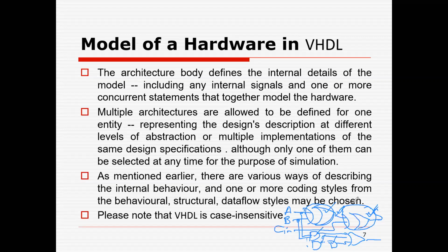I have already said that there are various ways of describing internal behavior, and one or more coding styles from the three styles which I mentioned. These are the three styles: behavior, structure, and data flow. So what are these styles? We will talk about later. Another thing, please note that VHDL is case insensitive. So if you are writing a signal with small or capital letters, it is one and the same thing. It will be taken as the same signal.